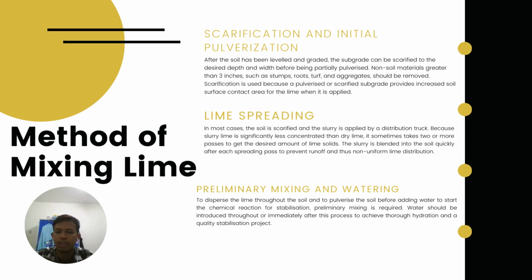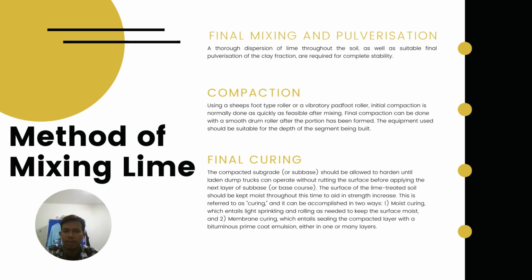Third is preliminary mixing and watering. To disperse the lime throughout the soil and to pulverize the soil before adding water to start the chemical reaction for stabilization, preliminary mixing is required. Water should be introduced throughout or immediately after this process to achieve thorough hydration and a quality stabilization process. Next is final mixing and pulverization. The thorough dispersion of lime throughout the soil as well as suitable fine pulverization of the clay fraction are required